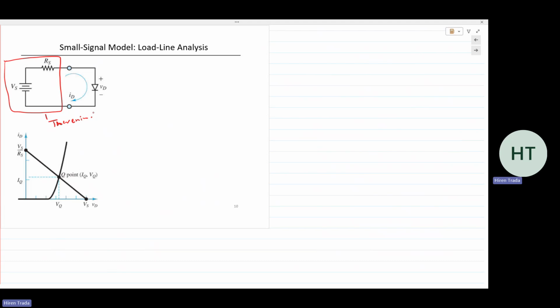So it's a series circuit. The current that is flowing through the diode is the same that's flowing through the voltage source, is the same that's flowing through the resistance. Okay, it's a series circuit, so all the current is the same, which is similar to what we did in lab 3. Okay, so that's the simplest diode biasing circuit. Now, analyzing a diode means to determine the diode voltage and the diode current, ID. There is a specific term for that, and that is known as the Q point.